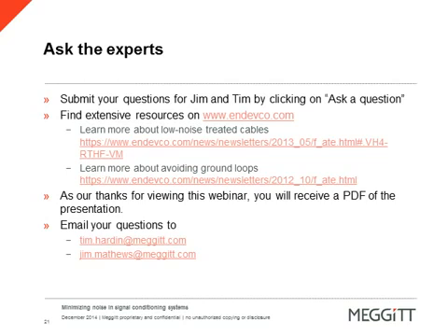Follow-up question to the previous, just for clarification. If the accelerometer is on an isolated stud, the signal conditioner should be set to ground. Vice versa, if the accelerometer is not on an isolated stud, the signal conditioner should be set to isolation. Thank you. I'll take that, Jim.